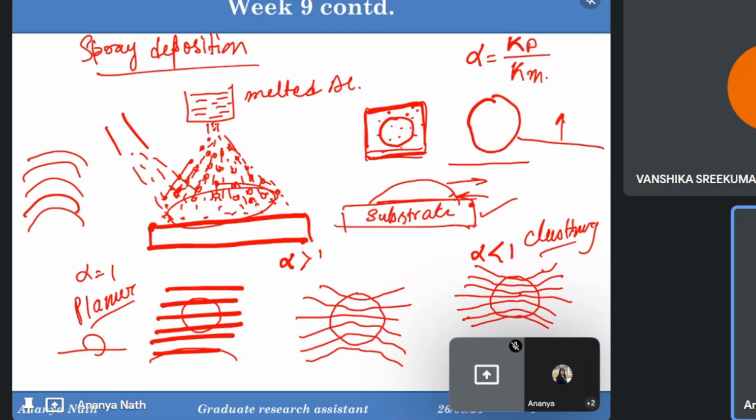It is happening, but there is not some particular bond like Mg to Si in the case of non-heatable alloy. But there is some atmosphere of the solutes that can hamper the dislocation movement, but it is not like some compound which is being made. You can also go for the heat treatment of non-heat treatable alloys as well. It's not like people do not go for heat treatment. They do go for heat treatment, but for another purpose, not for precipitation.